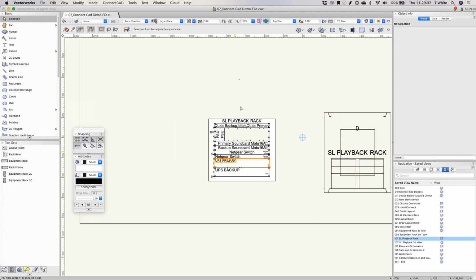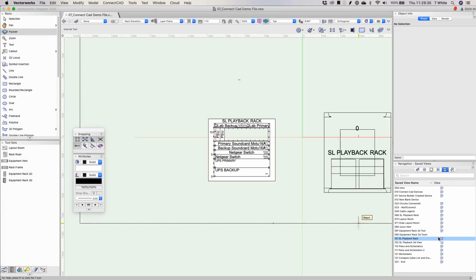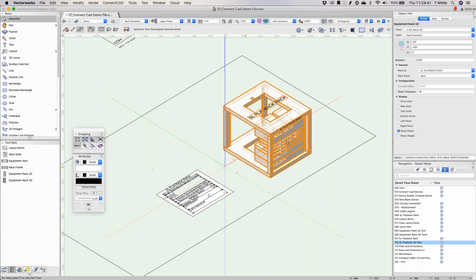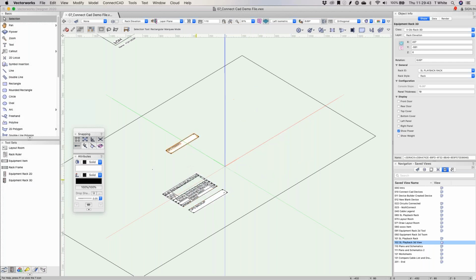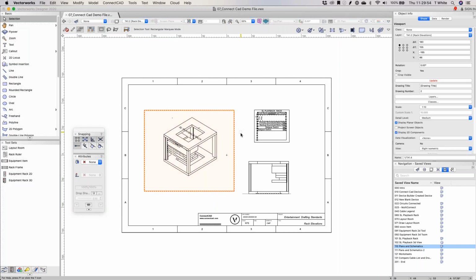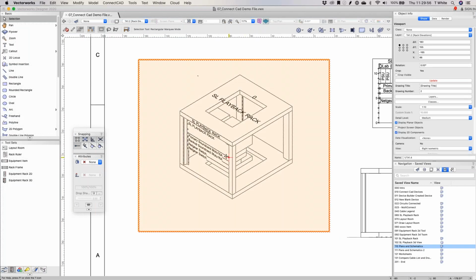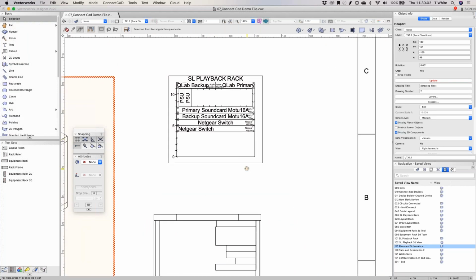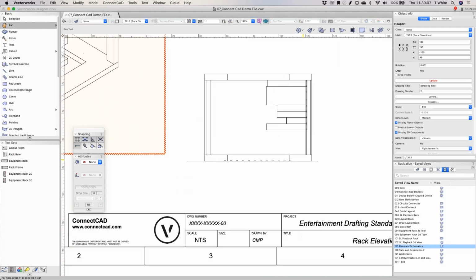Okay, so I've basically got my assembled rack model here. If we have a look at this in 3D, you will notice that this is basically referencing this. So if I now remove pieces of equipment from the rack, it actually removes it from the 3D model. This kind of workflow makes it really easy to create schematics, and not just schematics, but drawings. So we can have an isometric view. You can have a front view, for example, so the installation engineer knows what goes where. You can put individual rack elements, and you can have a side elevation.